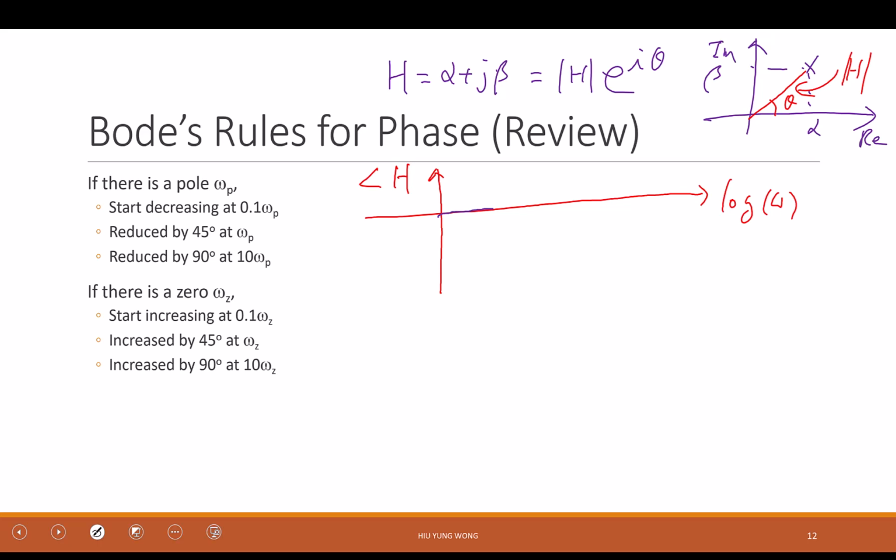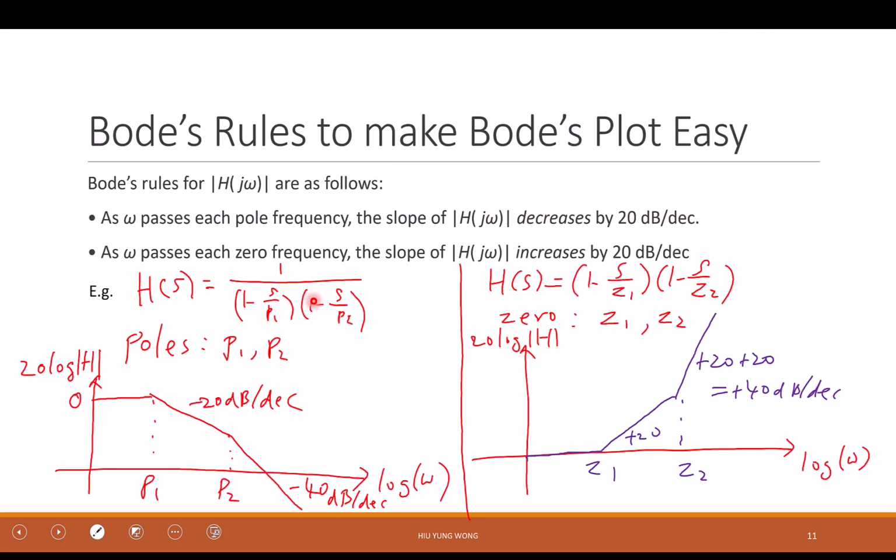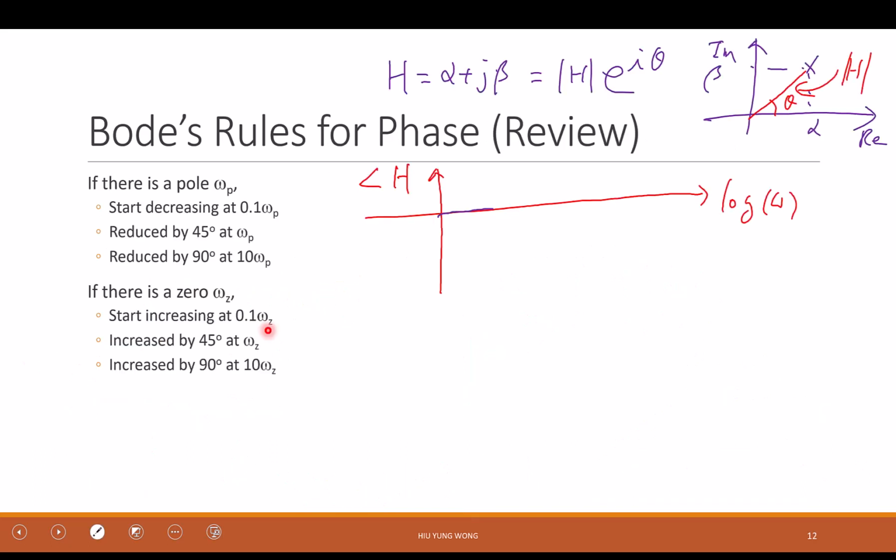Let's say like the equation we have here, right? When you have 0 frequency, the gain is 1, right? 1 is a real number. What is the phase of a real number? 0. Because it's all on this real axis, right? So theta equals 0. If it's purely imaginary, it's all on this axis, right? Then it will be 90 or negative 90, depends. Anyway. So I said the wrong thing. For real, if it's positive, then it's 0.